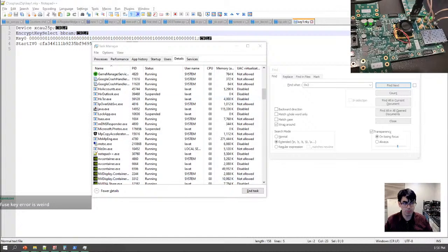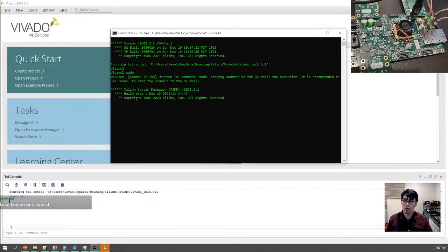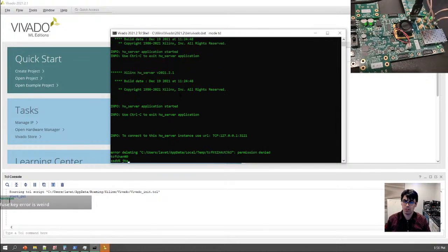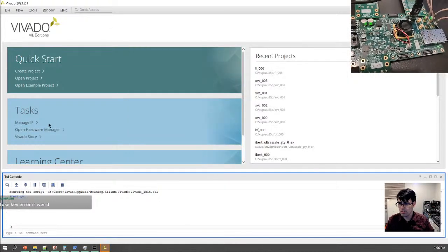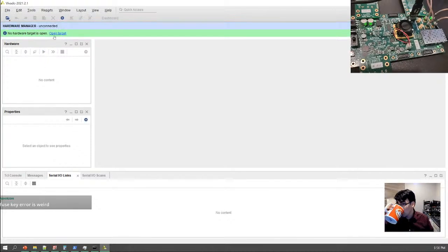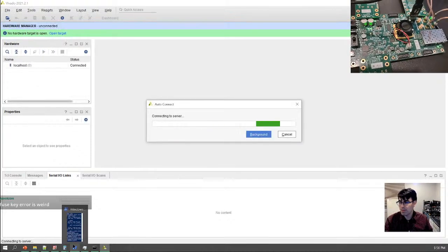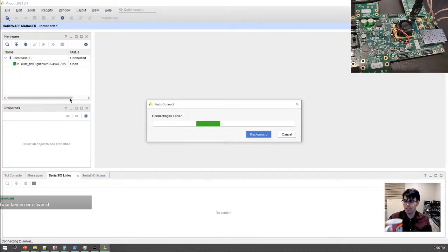Vivado, let's get a Tcl shell up here. If we do XSDB, I want to make sure we're clean on the JTAG targets. Okay, one JTAG target. It's the first device. Okay, let's try it. I think this was the issue that was specified in that forum, that the JTAG chain can get confused on multiple devices.